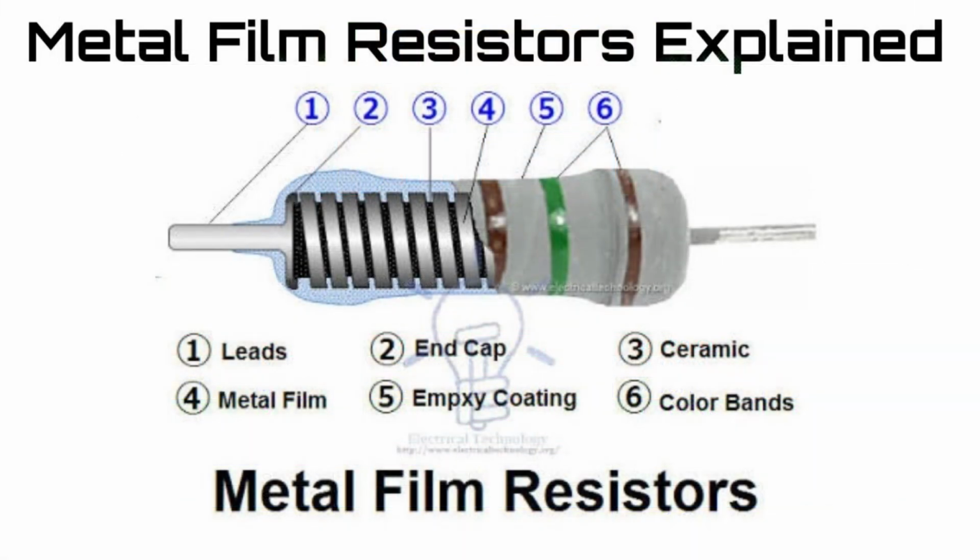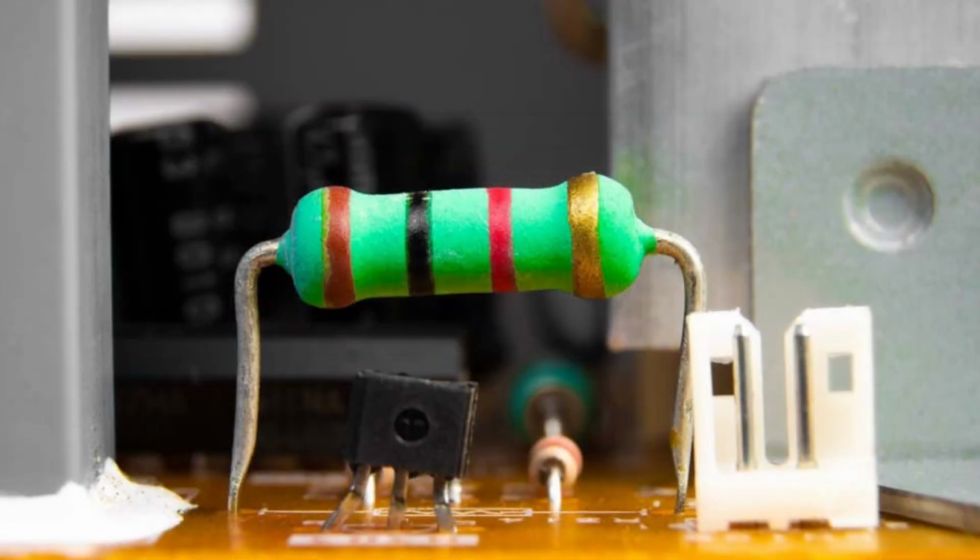Film resistor, the generic term, consists of metal film, carbon film, and metal oxide film resistor types, which are generally made by depositing pure metals, such as nickel, or an oxide film, such as tin oxide, onto an insulating ceramic rod or substrate. This method of manufacture allows for much closer tolerance resistors, 1% or less, as compared to the simpler carbon composition types.